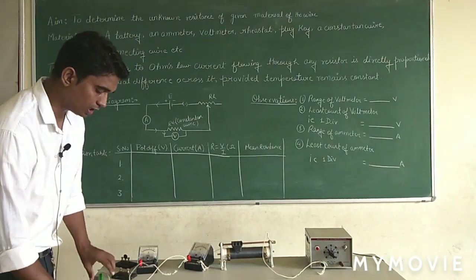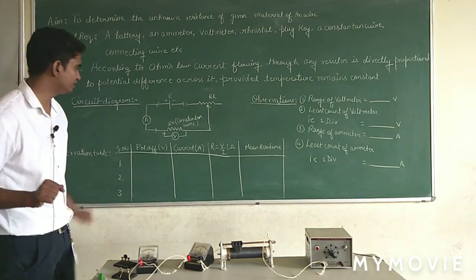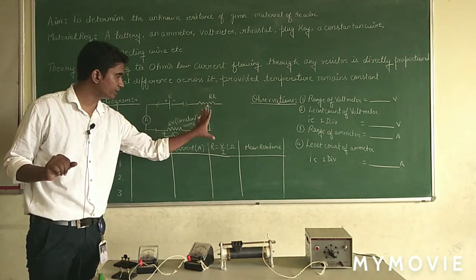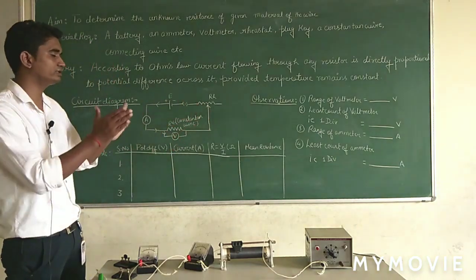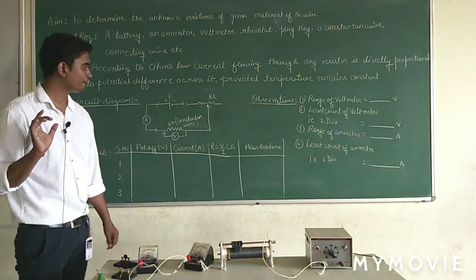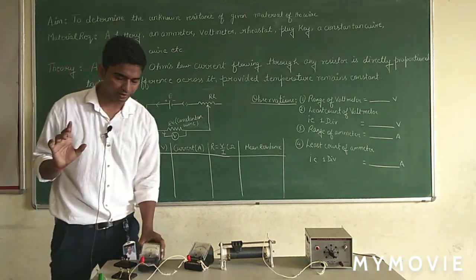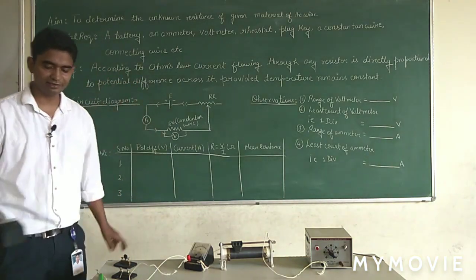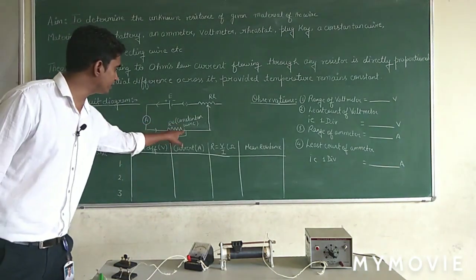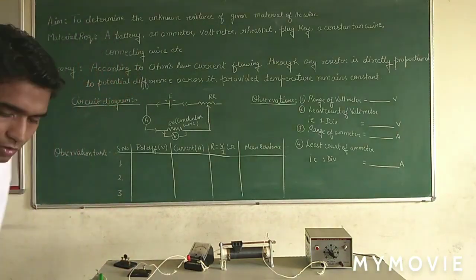Now how do we connect these circuit elements in a circuit? Just follow this circuit diagram, see how these devices are connected, and connect all the devices in the same manner, and we will obtain our circuit. The basic idea is that all the devices are connected in series except the voltmeter. So keep the voltmeter aside and connect all the other devices in series. We have to connect the voltmeter in parallel across the resistor, that means this wire. We will deal with this later on.